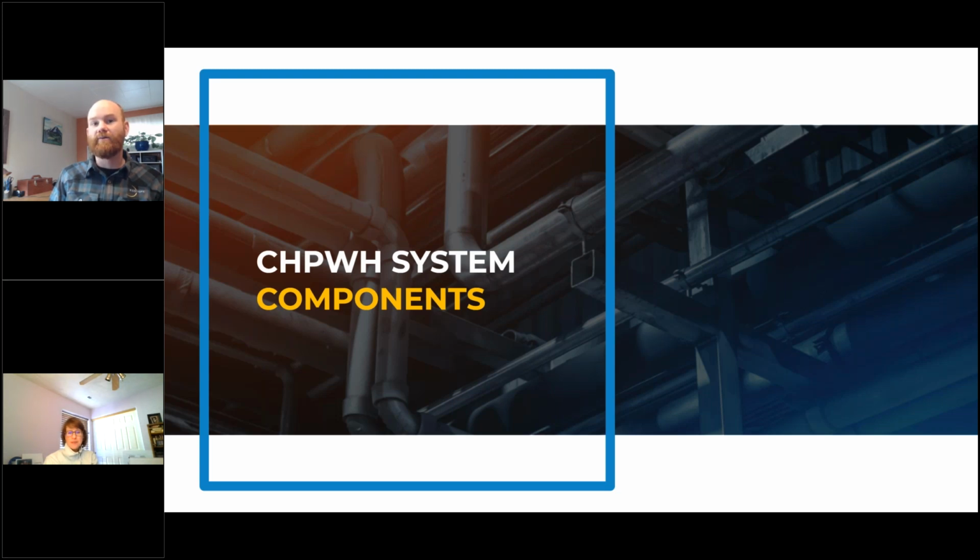Other failures are related to cycling. So a storage tank may reduce the cycling of the heat pump when it's turning on and off, but repetitive cycling in any type of equipment definitely reduces the operational life of that equipment. And so you really want to ensure longer heat pump run cycles and make sure that they're not starting and stopping frequently, multiple times or dozens of times throughout the day.